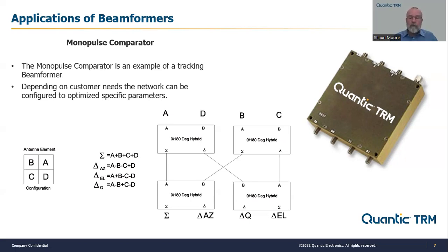This is very often used with a reflector antenna, or something else where we're trying to track the source and make sure that we're always on the peak of that beam to get the best signal coming in. So if you have a four element antenna array, a stack 2 over 2, that square element array is then fed into the 4 inputs of the Butler matrix.